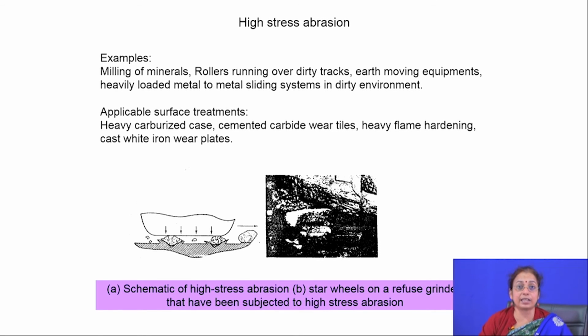So, apart from cutting, there is also deformation. Cutting action depends not only on the hardness differences, but also on the sharpness of the mating surface. The sharper the mating surface, naturally the more will be the scratching action, but if the stress is very high, naturally there will be deformation as well.